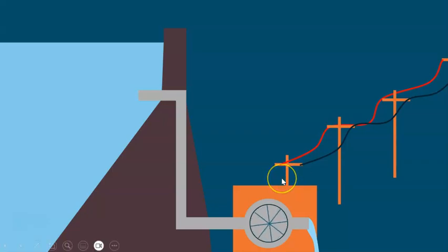If I maybe gear up my turbine so that I can run a higher speed generator, I must apply a greater resistance to the water flow. If I'm going to try to extract more energy, I have to be taking more energy away from that flow, so that means reducing the flow. Likewise, I can make it a bit easier, and the water will flow through a bit quicker, but I'm not taking as much of that energy away from the water.